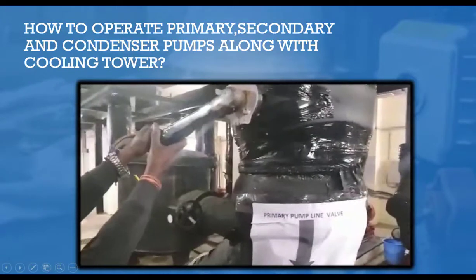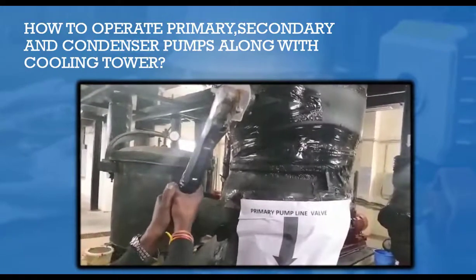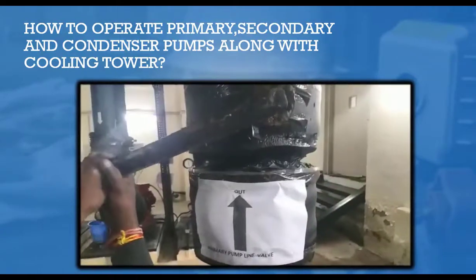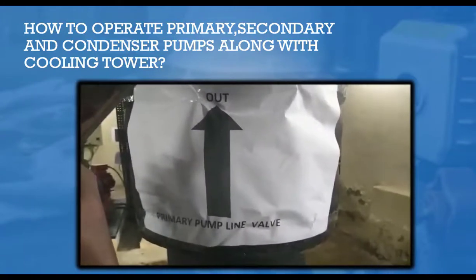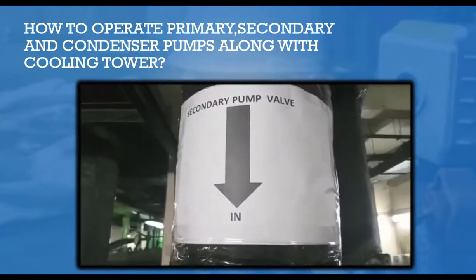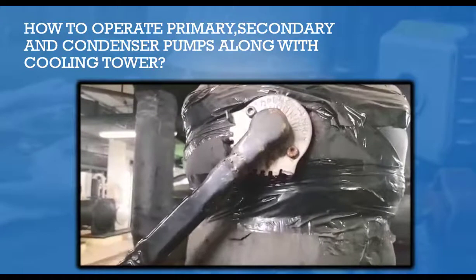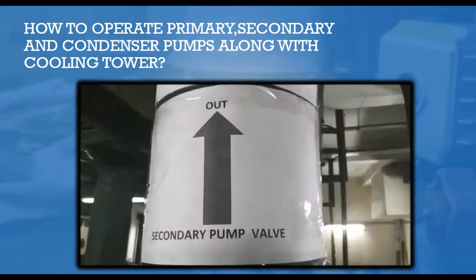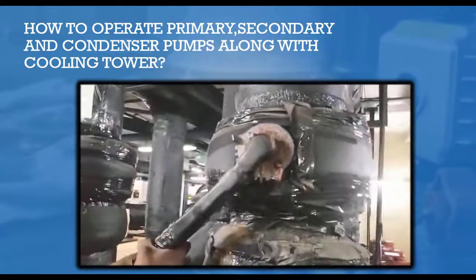Now before starting the chiller, you have to ensure the primary pump suction valve and delivery valve are open. Similarly, ensure the secondary pump inlet valve and outlet valve are in open condition.